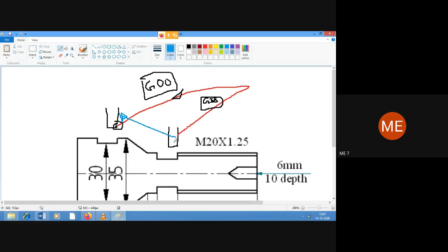Okay, so for that, one way is to take the tool to this higher position and move it in this particular direction. After finishing over here, this is G01 code. It has to be moved vertically upwards and then horizontally again in a linear manner. So again I will get over here as G01 and this particular value, right? I have chosen the second method because we are going to use the same tool again.